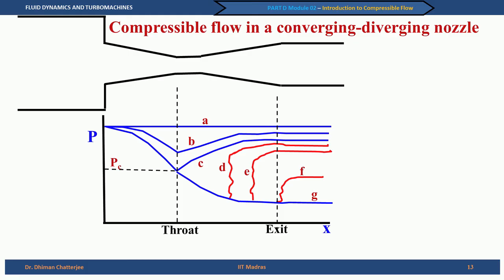because in this course what we need is to appreciate the fact that a CD nozzle, or converging diverging nozzle, is essentially useful to bring me a higher velocity than what a simple converging nozzle can give. And if the pressure is below G, like H, then the pressure will be adjusted by the formation of expansion waves. For details about this, you should see a good book on gas dynamics or compressible flows.